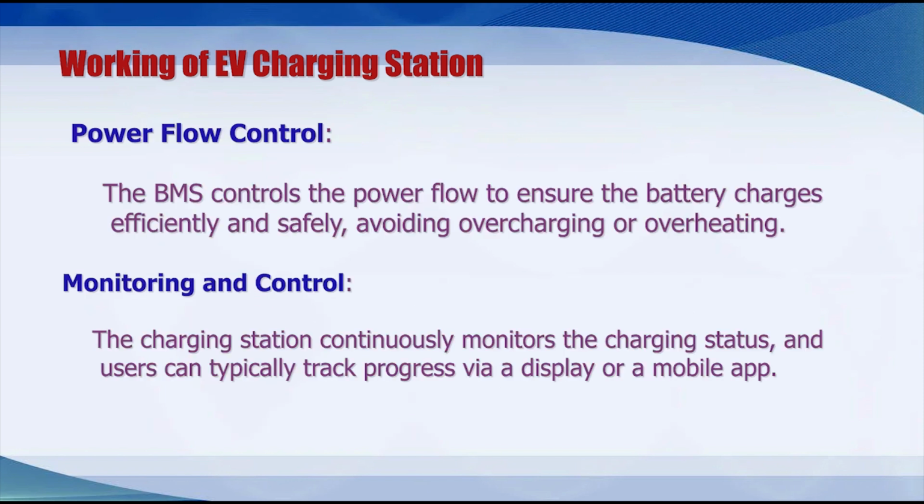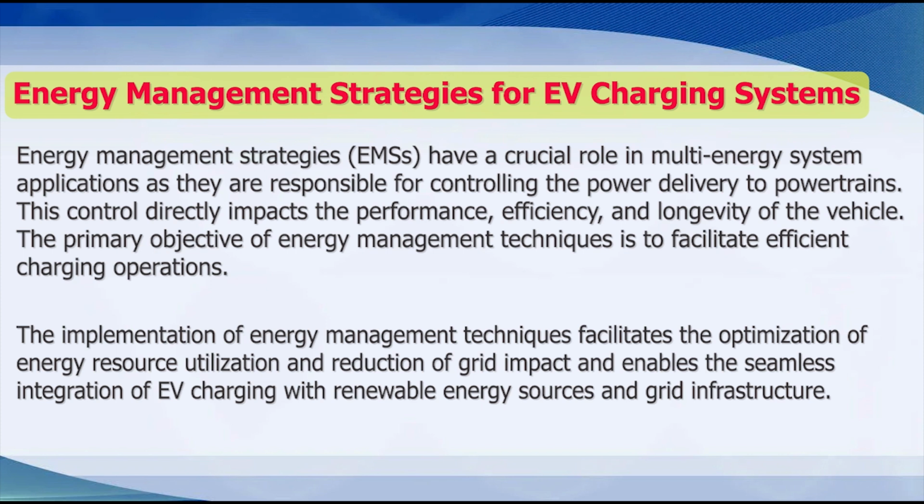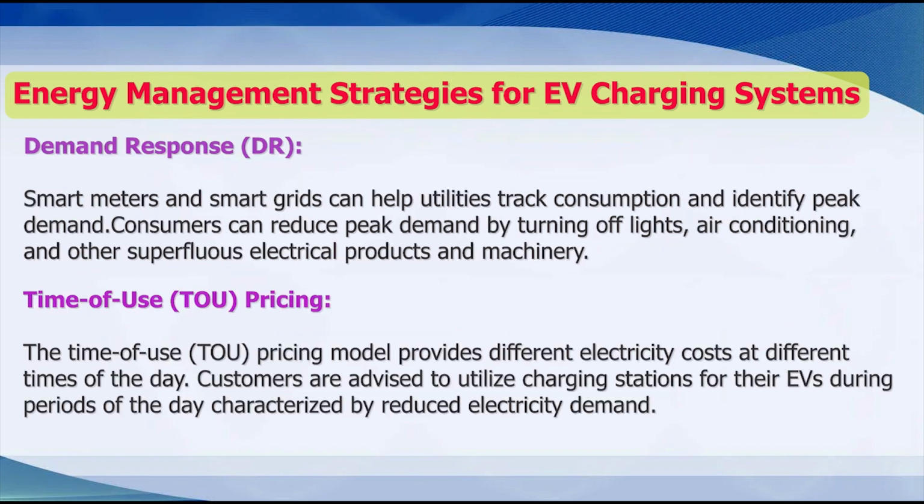We need to control the power flow, we need to monitor and control these devices, completion and disconnection, billing and authentication. Then energy management strategies are essential for EV charging stations, where we can assess the load demand and time of use pricing. A pricing model can be developed for different electricity costs at different times.